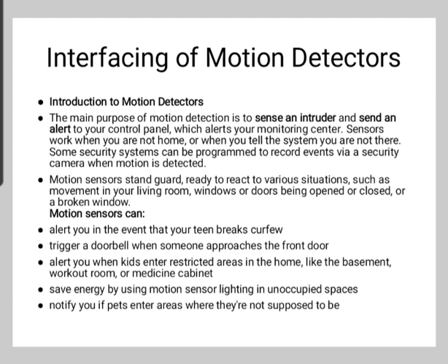The first one is passive infrared. Passive infrared sensors are sensitive to a person's skin temperature through emitted black body radiation at mid-infrared wavelengths, in contrast to the background objects at room temperature. No energy is emitted from the sensor, thus the name passive infrared, and this distinguishes it from the electric eye, for instance, in which the crossing of a person or vehicle interrupts a visible or infrared beam.